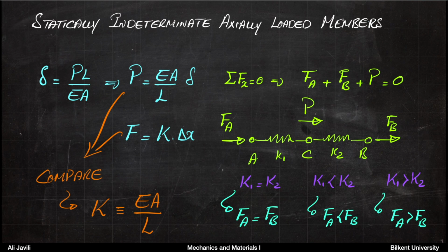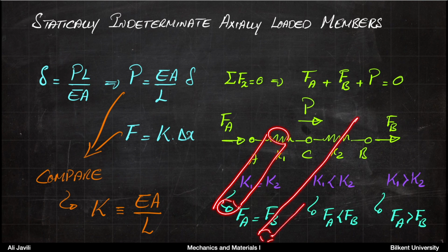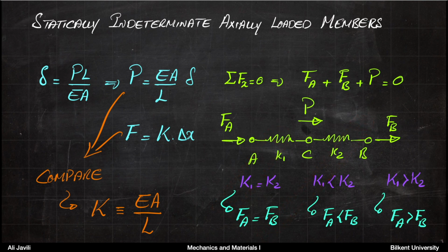Okay, so again, if you think of a truss member with a certain length L, and then if you use exactly the same material but now you make it longer, then making a member longer gives you less effective stiffness. Making it fatter makes larger stiffness, and making it stiffer by increasing the elastic modulus or Young's modulus of the member also gives you a higher effective stiffness.